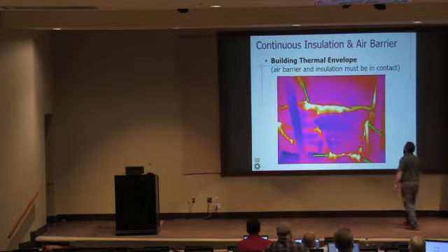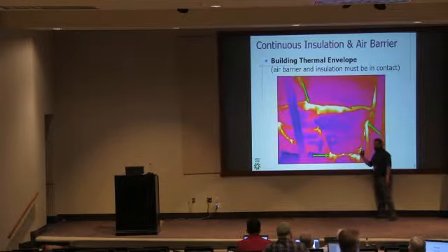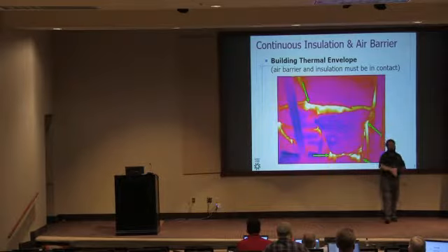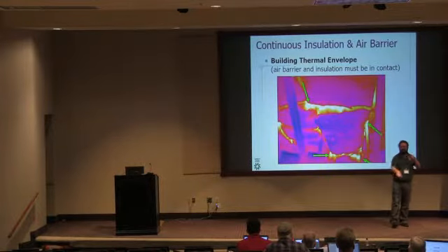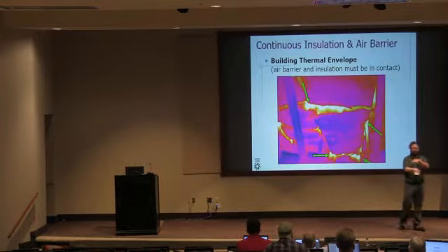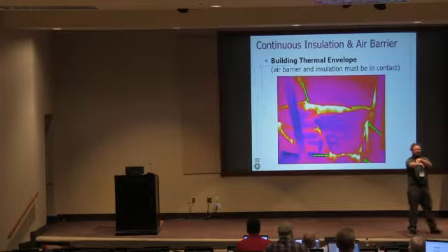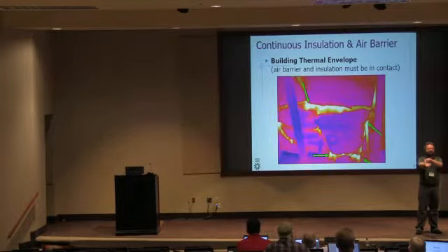And then you take the same picture and flip it over, what is it now? It's a crawl space. You're looking up at a floor. Same problem, right? Been in a crawl space and the bats are sagging down. They actually have no resistance to conduction unless they're installed in contact with that subfloor. And then you've got to compress them to keep them in place with the subfloor.